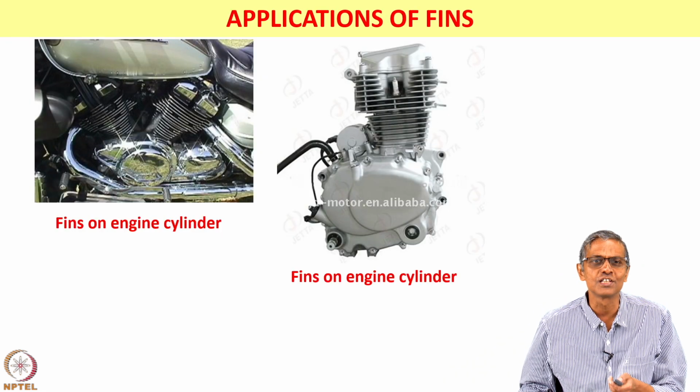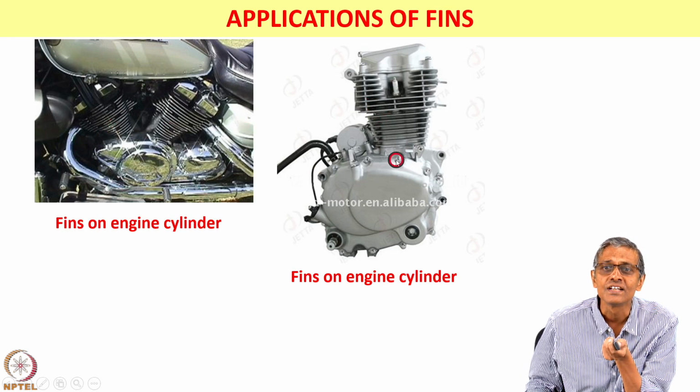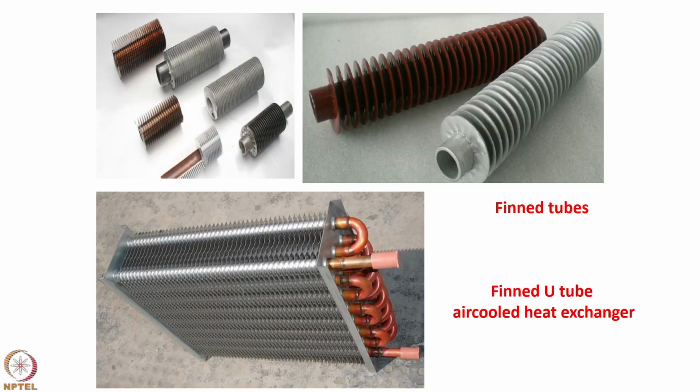So where do we use these fins? If you just take any scooter, you can see that the IC engine is cooled using these fins. Any pump, the motor is cooled by these fins. If you take any air cooled heat exchanger, there are fins. You can see fins on the aluminum tubes and the copper tubes in the air cooled heat exchanger. Okay. So fins are used to increase the heat transfer.